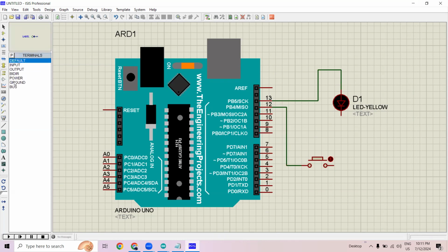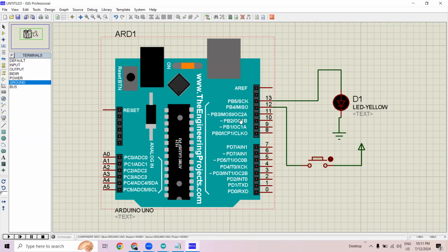And then I'm going to connect this button with power, as this button is going to give the logic to your controller board. That means in this case, the Arduino board is going to receive the logics from the button, and pin number 12, which we connected with this button, is going to work as input. If the button is giving any logics to the controller, the direction of current is inward to the controller, and the button must have power to give any logic.